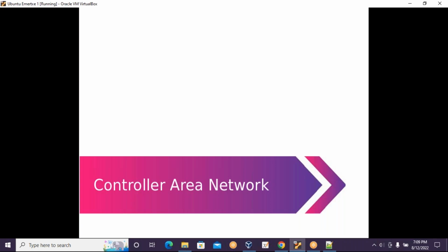Okay. So we saw how to configure the I2C in our microcontroller. Then the RTC by default communicates with the I2C protocol. So whenever you have to read from the RTC or write into the RTC, you have to go with the specific registers and you can write into that address. The addresses of the registers were given. You could write into those registers or read from the given address. So we discussed that so far.